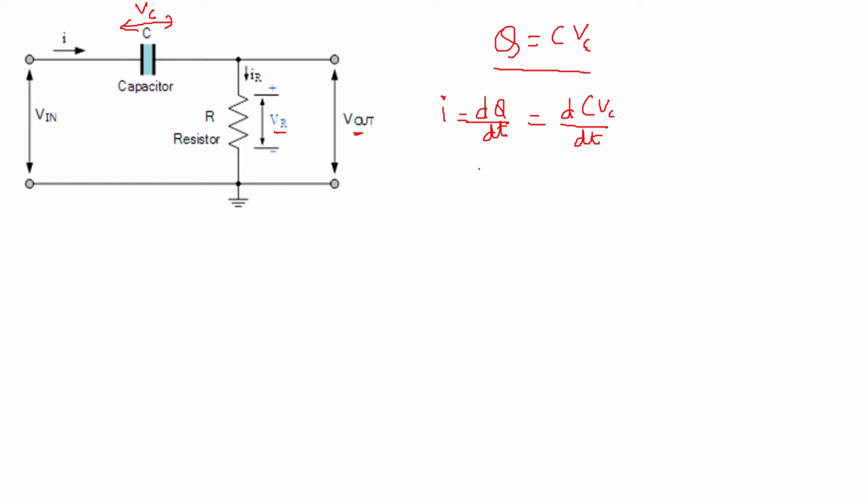Here, the reactance of the capacitor, XC, that is the opposition to the flow of current produced by the capacitor, is much larger than R. In that case, the voltage across the capacitor will be approximately equal to the input voltage, because almost all the voltage will appear across the capacitor and a very negligible voltage across the resistor. So VC is equal to Vin.